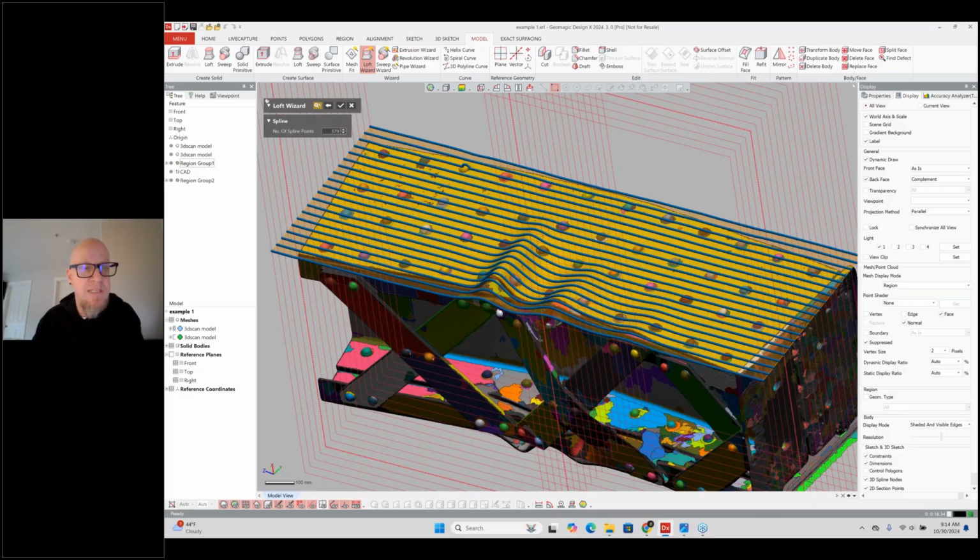And placing 379 points each, I will change that to 200 just to have a little bit smoother surface. It will probably be hard to see the difference, but you can see fewer points here, and I will accept, okay? Now the software is finishing this step, and then we will have one single surface here that we can start to create the thickness and extract the first side.